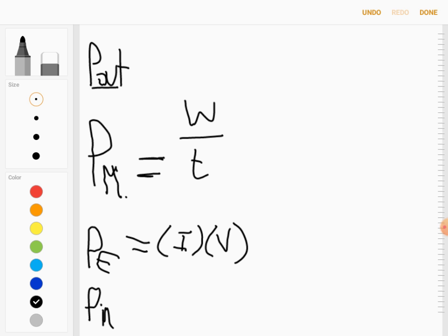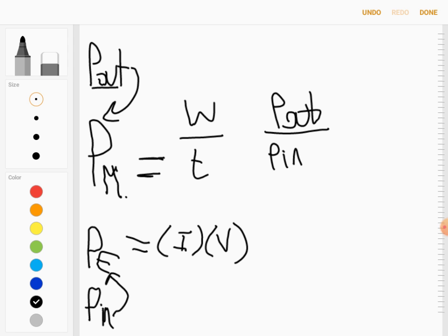And so you first calculate the P out, which is the same thing as mechanical power, and then you calculate this. Then at the end you do the efficiency, which, remember, you can also use P out over P in, which would be mechanical power over electrical power. You multiply that by 100. Then that's how you get your final efficiency answer, and then you have some conclusion questions on that activity.